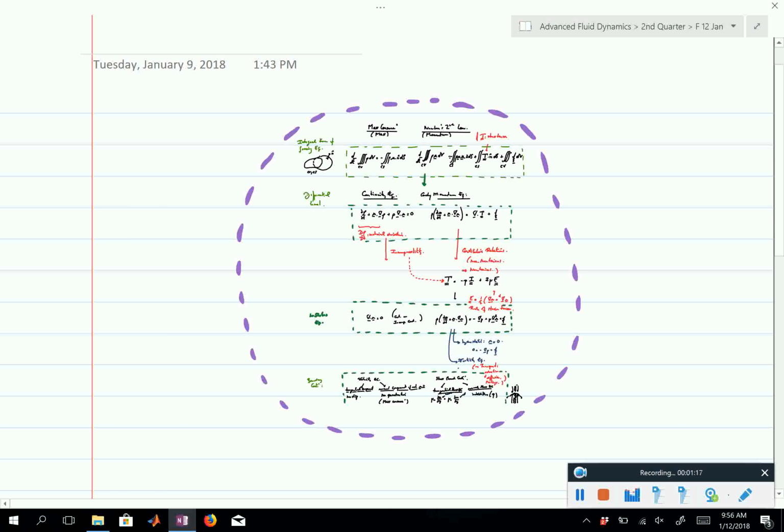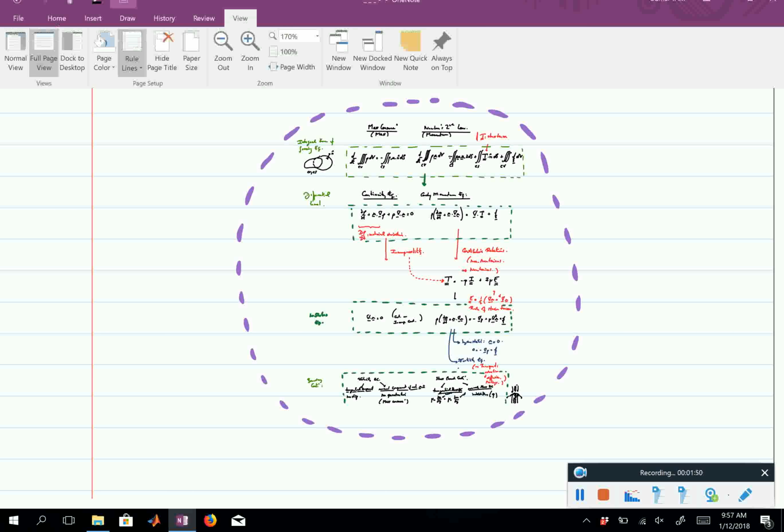And sometimes it's just mental, but you need to have a mental exercise of, okay, especially what is the Reynolds number? Because a lot of what we followed sort of Reynolds number lines. But even when you're looking at an interface, gravity waves, for instance, well, what is the Weber number? Is surface tension important, or is inertia so much larger than in the wave propagation that I can probably neglect the effect of surface tension? Right? So every time you want to solve a real problem and you want to take some of these equations and try and solve that, usually you want to go through the filter of dimensional analysis.